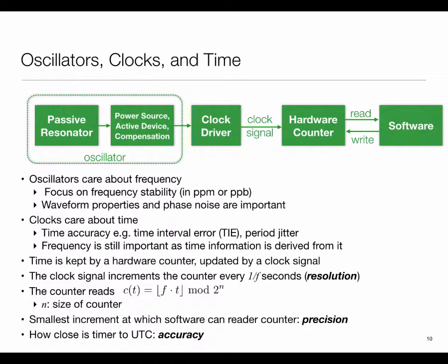So what we have out here is something which is incapable of keeping long-term time, so you would have some support in the software, which is what applications see. Otherwise, the applications would have to bear the burden of things rolling over very rapidly. A 64-bit counter running on a gigahertz processor rolls over reasonably infrequently. But most of the processors we are dealing with have 32-bit counters or maybe 16-bit counters, so they roll over very rapidly. So there are two things that end up mattering by the time we are looking at the software reading this counter.